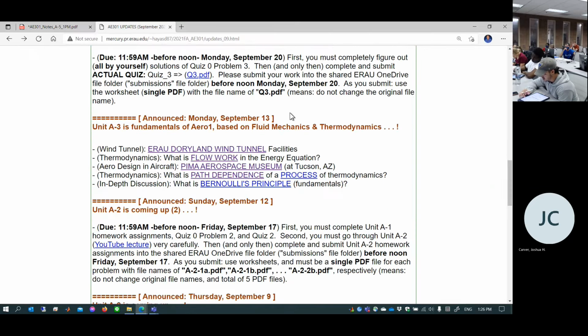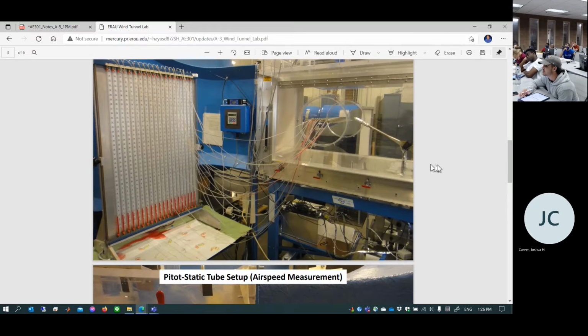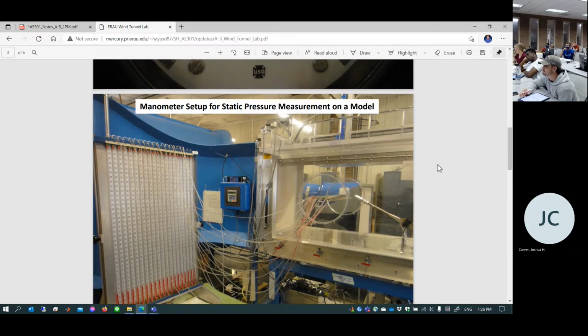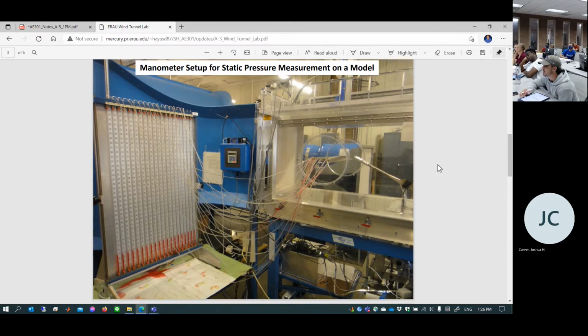Let's go back and take a look once again. In a wind tunnel, you have two different ways to measure aerodynamic forces. One is a direct measurement. Suppose you attach this test model to the side. Well, there's no device attached for force measurement, so in this case the purpose of your test is to measure the pressure. That's the only thing you can do.